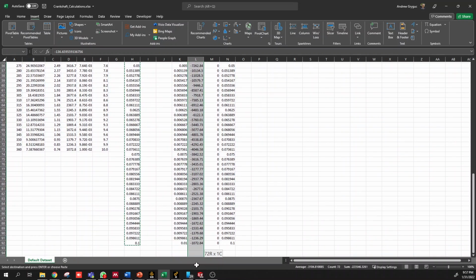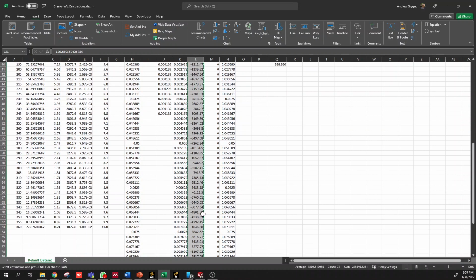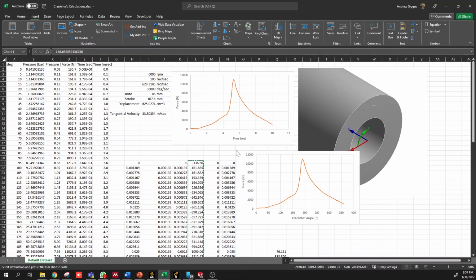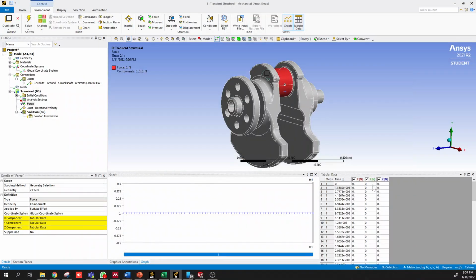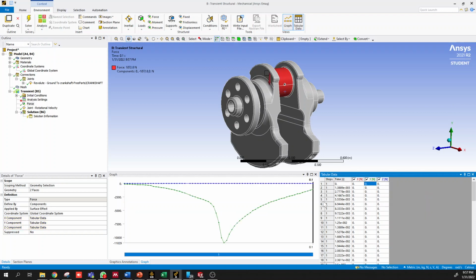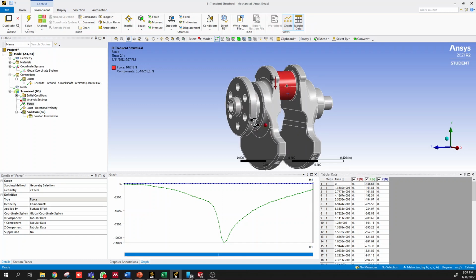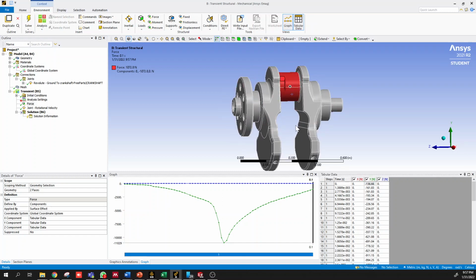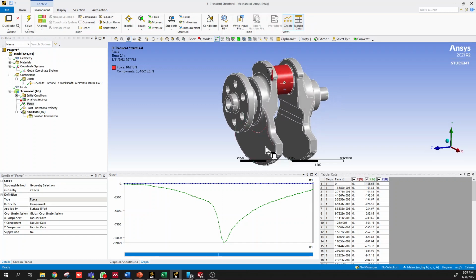Similarly, I have the forces here. I know the sign convention shows it as positive in this graph, but we've negated it just to get the vector in the right direction, because up is positive. So we'll click paste here, and now you can see our force versus time populate, and the vector that's being shown here graphically is downward, which is what we'd expect.